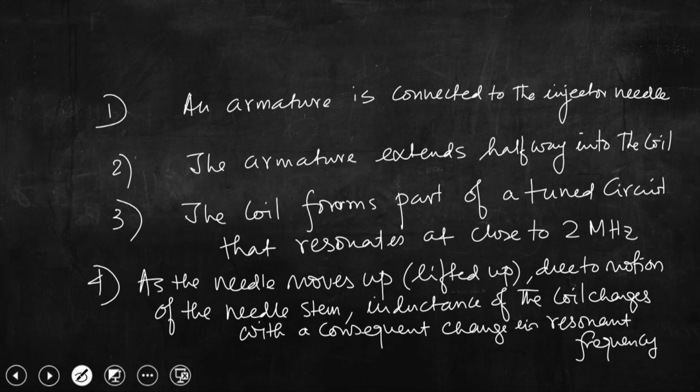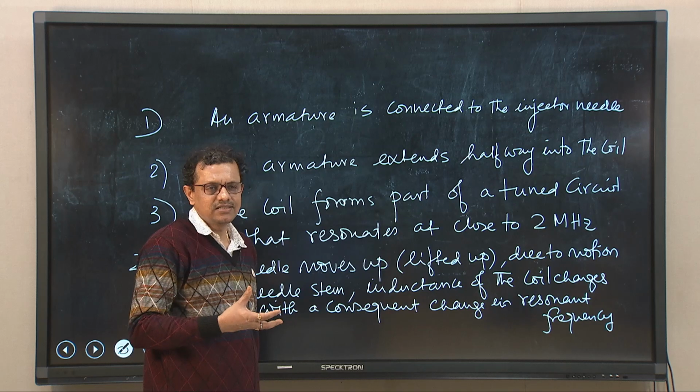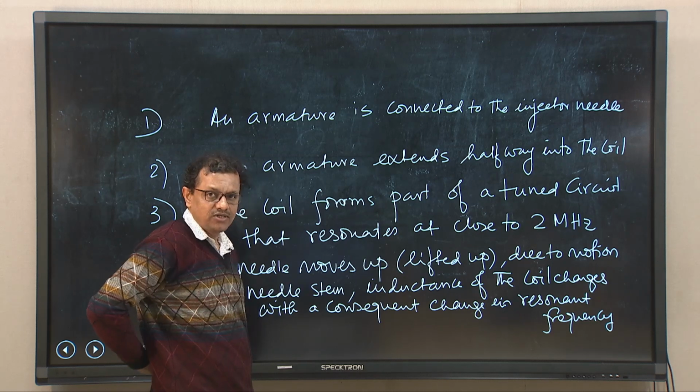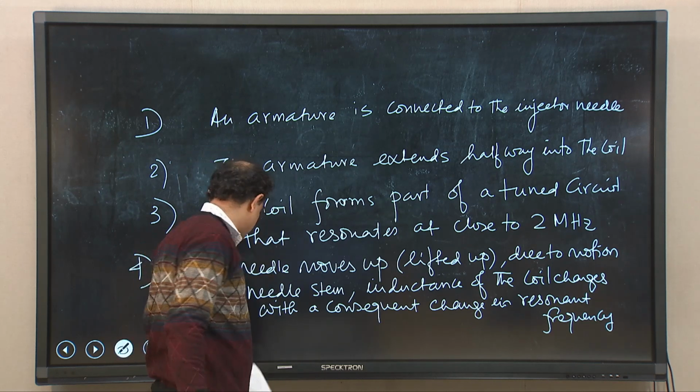So essentially you are trying to measure the change in resonant frequency or change in inductance in the coil. As the inductance will change, it will change the resonant frequency also, that is why it is a frequency modulated system.